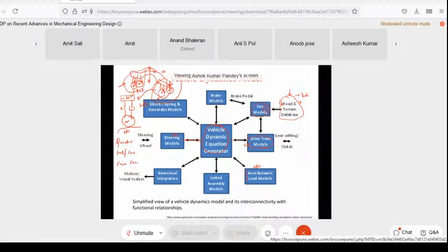But if you divide this into two parts, where you have one mass, and then you consider another mass over here, which is like some portion, some brackets that is just below the suspension. So here you have the suspension system, then you have the auxiliary masses, and after that only the tire comes up, right? So the wheel comes up over here. If you have this mass and this mass, we can call them m1 and m2. So we define such a model as a 2 degree of freedom quarter car model, right?